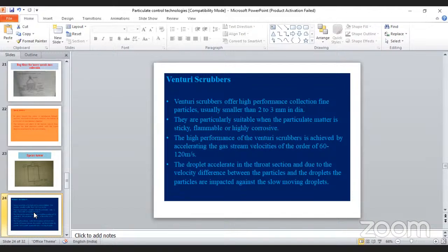When it enters the impinger, that glass bottle, we have to provide the solvent or water. Water is also a solvent, like how sugar and salt are dissolved. And the inlet should be provided till the end, the bottom of the bottle. It should not touch the bottom of the bottle, but it has to be provided almost to the bottom. But the outlet should be provided at the top only. There should not be any tube which would enter into the collection medium. Collection medium is water or solvent.